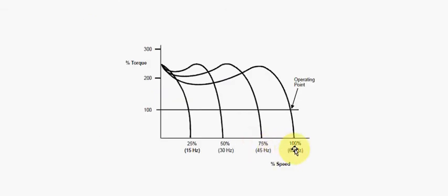So that's 60, 45 Hertz, 30 Hertz, and 15 Hertz. So here we're moving the volts and frequency up and down, and obviously changing the volts with respect to the frequency. So here you can see we potentially have constant torque. This guy reckons he's working at 100% torque.